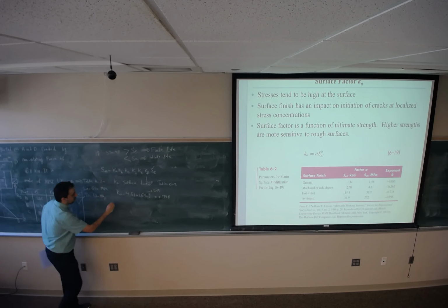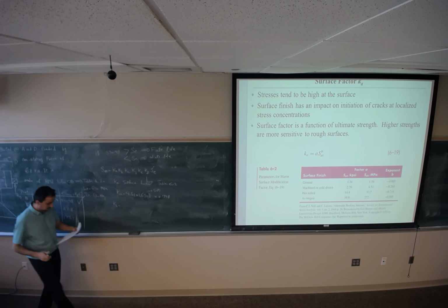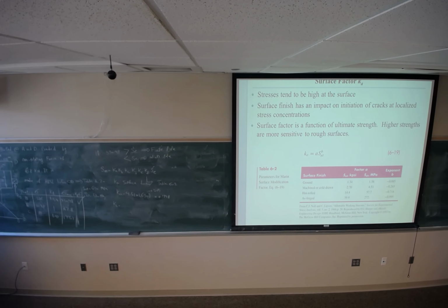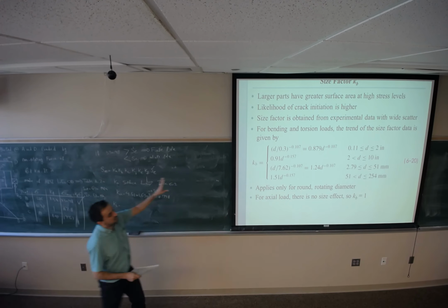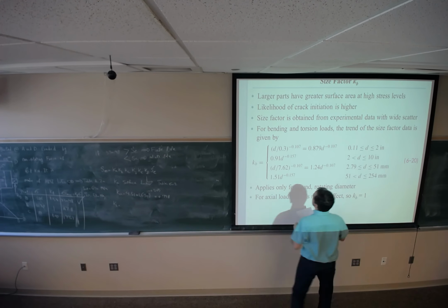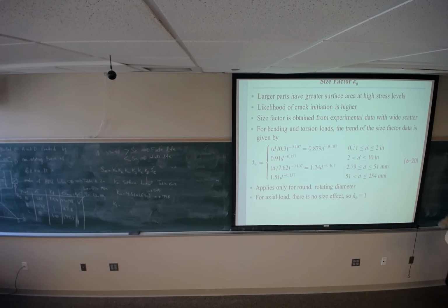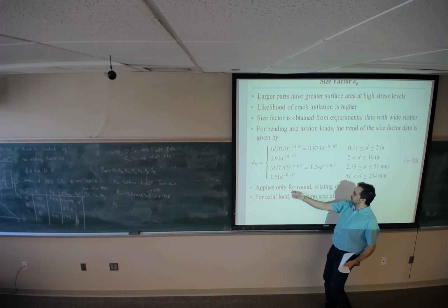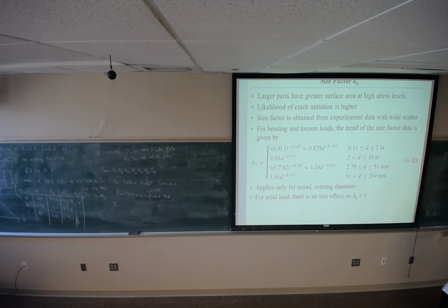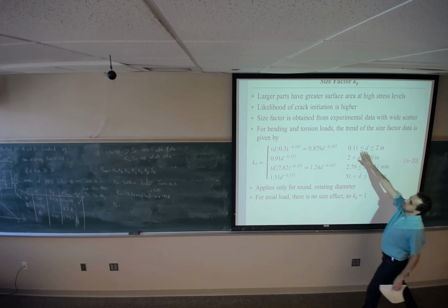KB, size factor. You should be careful when you are using equation 6.20. It's applied for round and rotating shafts, for bending and for torsion loads.